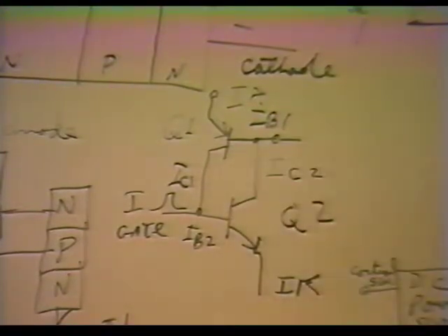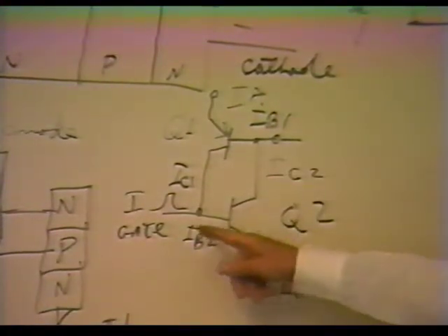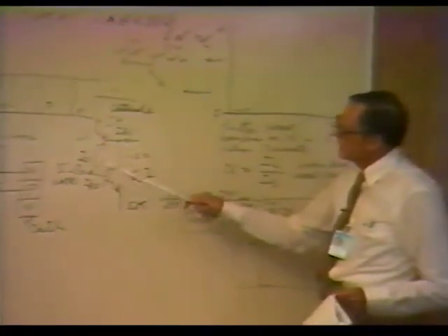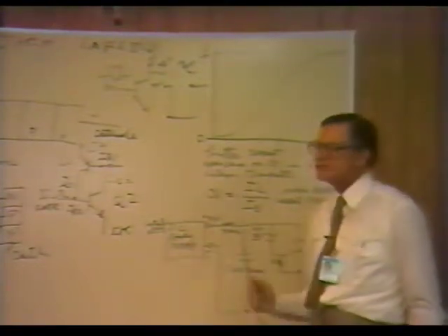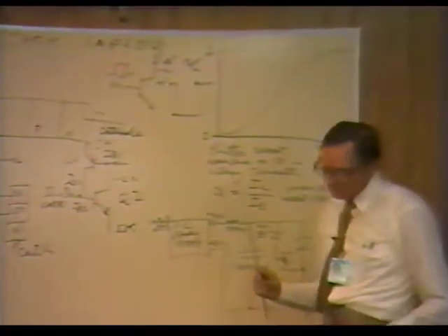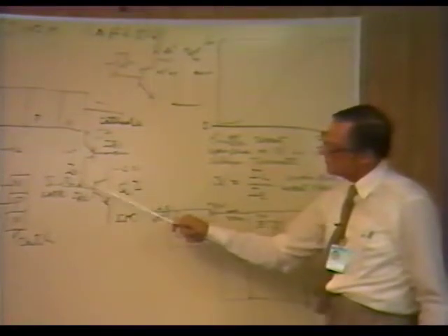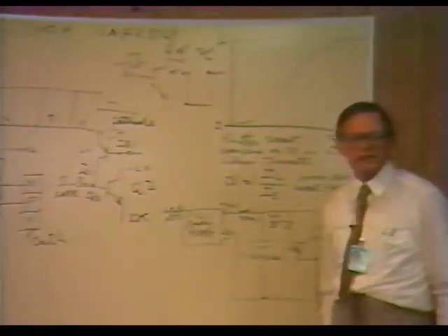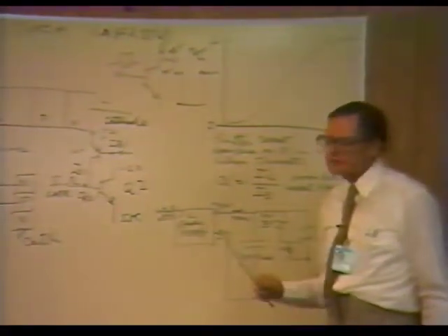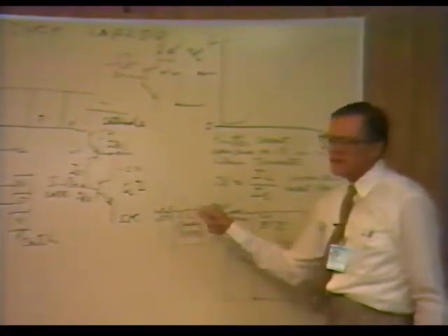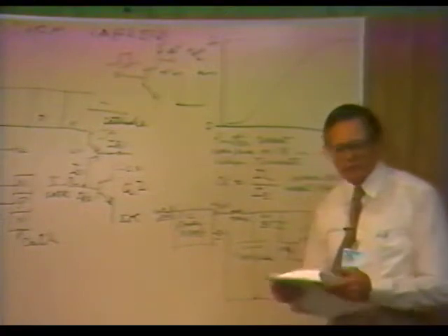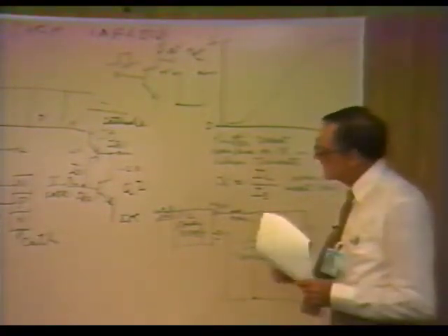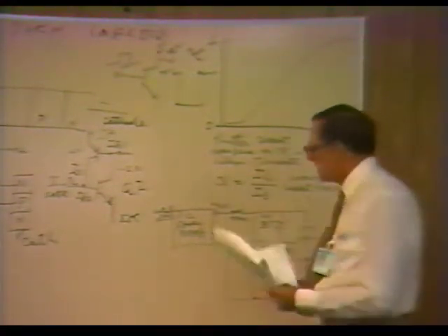Just as in the hydrogen thyratron tube, the gate no longer can control the operation, and the device stays on. So when you use an SCR, once you turn the gate on, the gate loses all control, and you cannot turn it off with the gate. The gate has no function whatsoever after the device turns on. Now, how you turn them off, we'll talk about later.